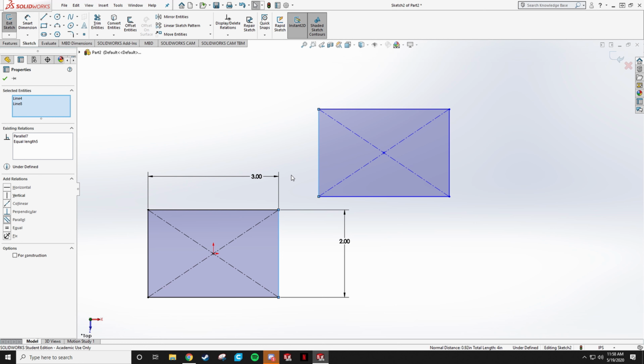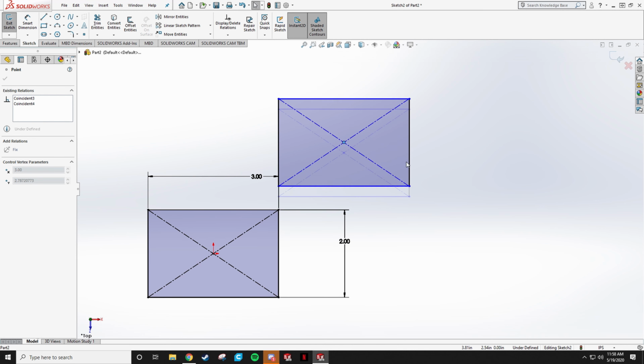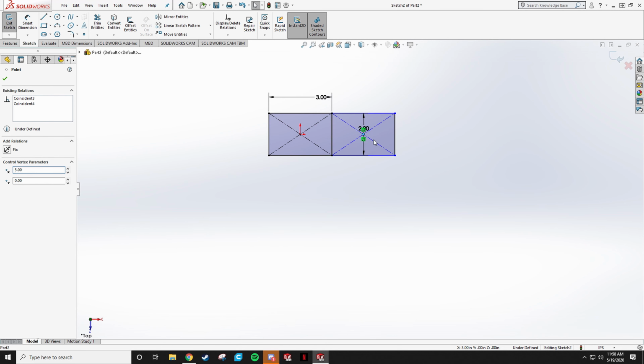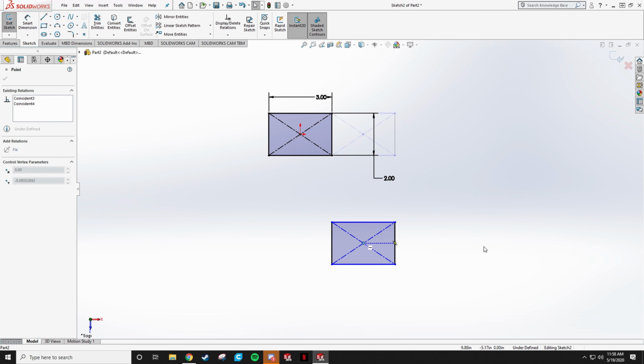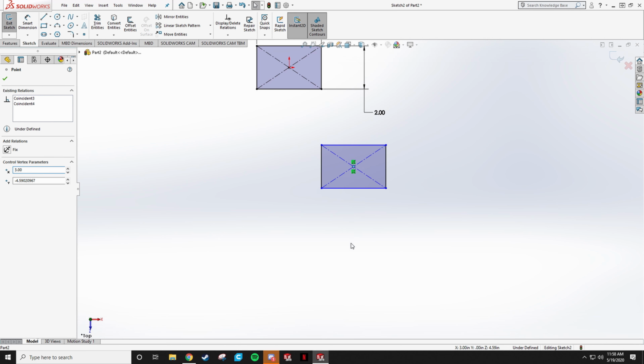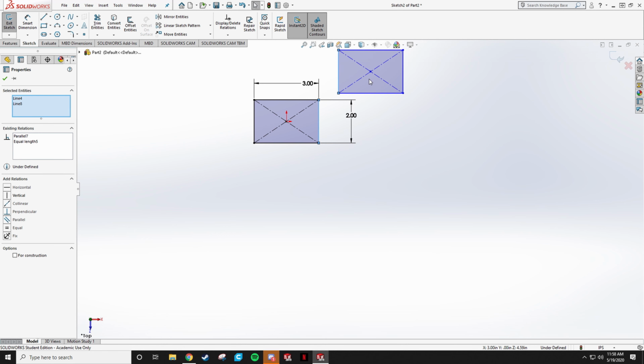If you want them to be collinear, you can tap that too, and that forces this to be collinear with that. So even though this triangle can move around, it will always be collinear. You can see me trying to drag my mouse this way. It's not going to do that. Before, I had the collinear, so let's get rid of that collinear constraint.